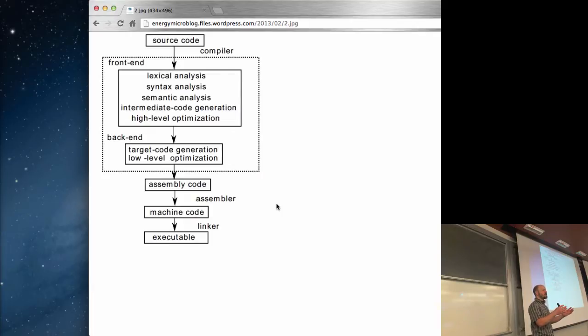You can do optimizations, and if there are multiple different levels of code that you have there, and then somewhere you have not declared a volatile, and bam, gone it is, and your code is gone. So then you have to go back into the disassembled code and see what the optimizer actually did with your C code. Happens more often than you would think. Okay.